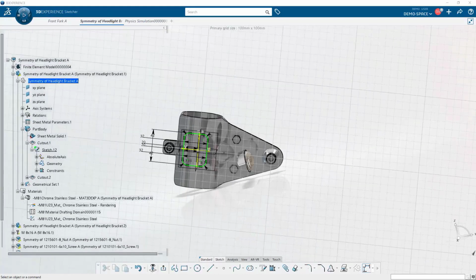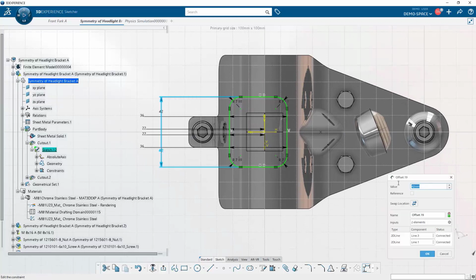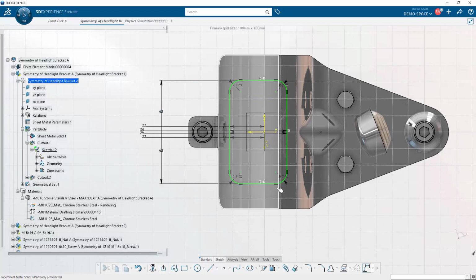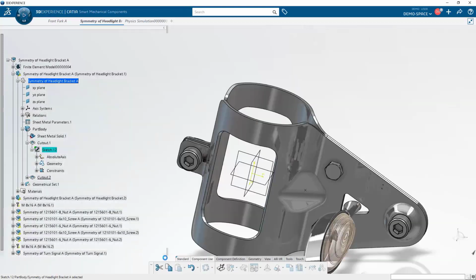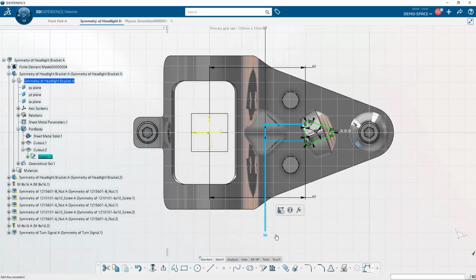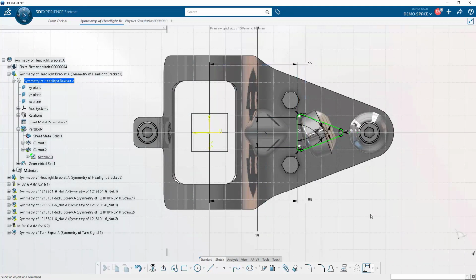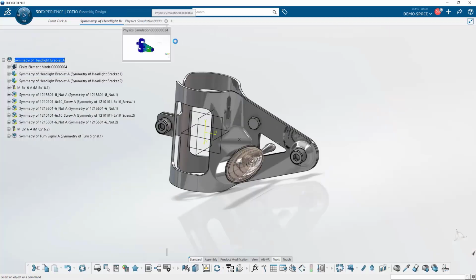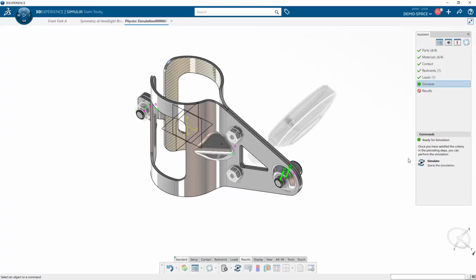This bracket design can be modified to reduce the amount of material used. Quick and simple redesign steps like increasing areas for the cutouts or reducing the thickness can be employed. The simulation created earlier recognizes the changes made and the designer is notified that the results displayed are out of date. The model is simulated again directly without the need to describe the loading conditions over.